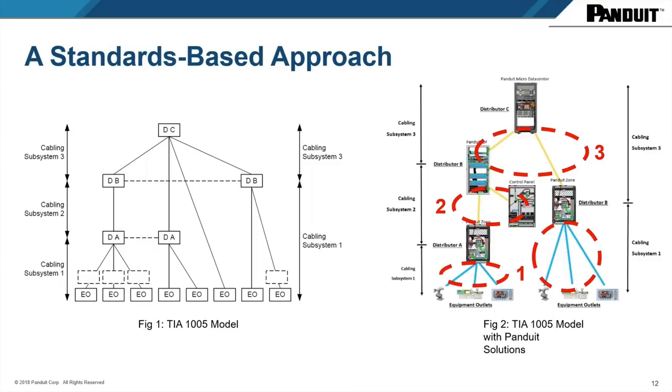The specifications 568 and 1005 state that when you run copper cabling, you shall not exceed a length of 100 meters. Running fiber, you could go at higher distances. So shorter distances are generally copper, and this is an extreme condition. Now we're talking about edge connectivity, where you have a category 3 for all of the M.I.C.E elements, to a fiber that is now connecting above the subsystem 1. So anything from cabling subsystem 2 and 3 can now be running fiber between those devices. You could also run copper if these distances are not, like I said, over 100 meters. So in a small factory, you might decide to run copper throughout. But generally, we are on fiber between these enclosures.